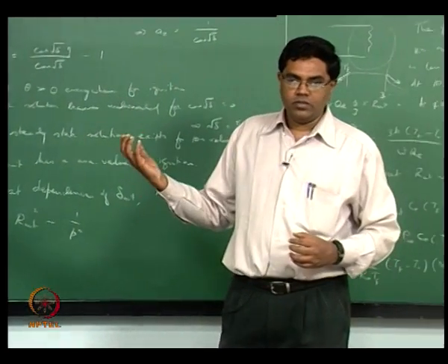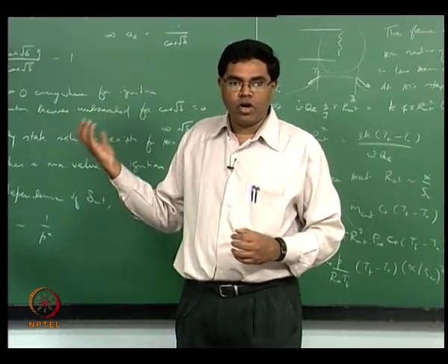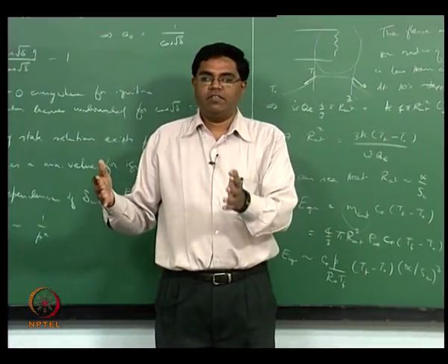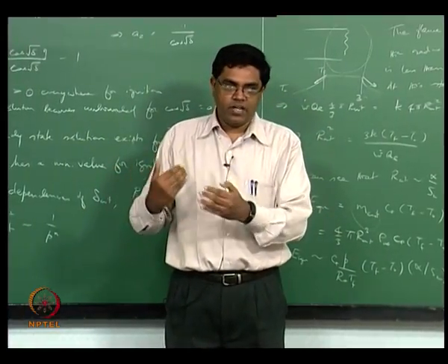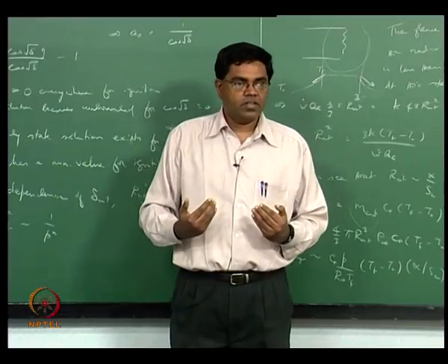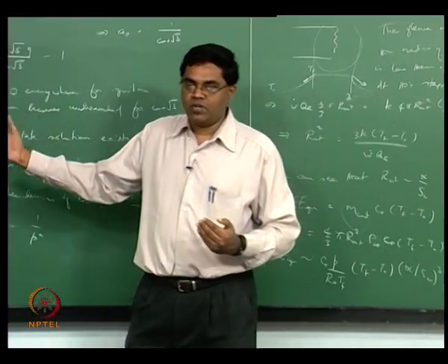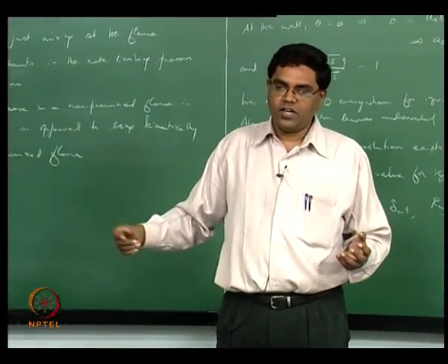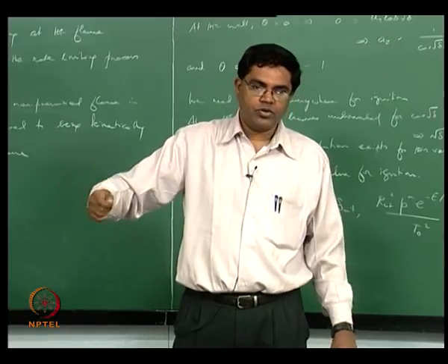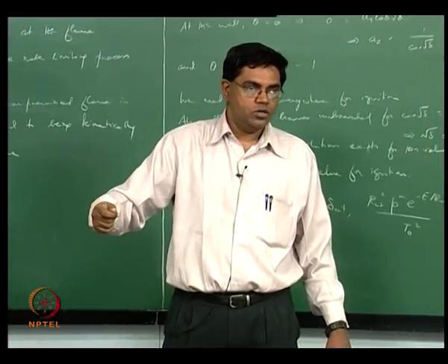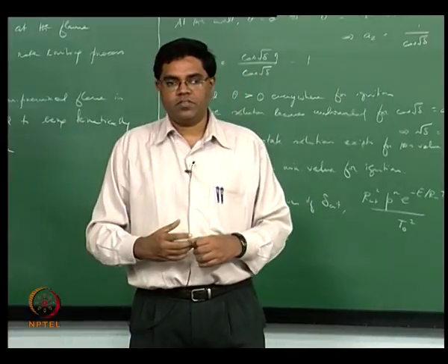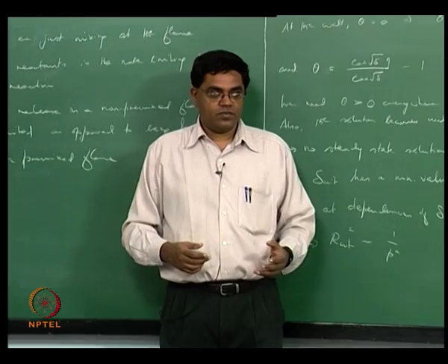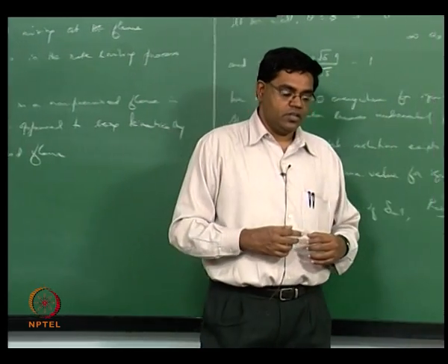are these very common? In fact, these are actually more common when compared to the premix flames. Premix flames pretty much have to be contrived many times. Somebody has to mix the reactants, right? Whereas diffusion flames are the ones that happen naturally in nature, right? So if you want to, for example, light fire to a block of wood or something like that, that's essentially a diffusion flame that's going on, right? And candle flames are the best example, right? So the candle flame is essentially a diffusion flame.